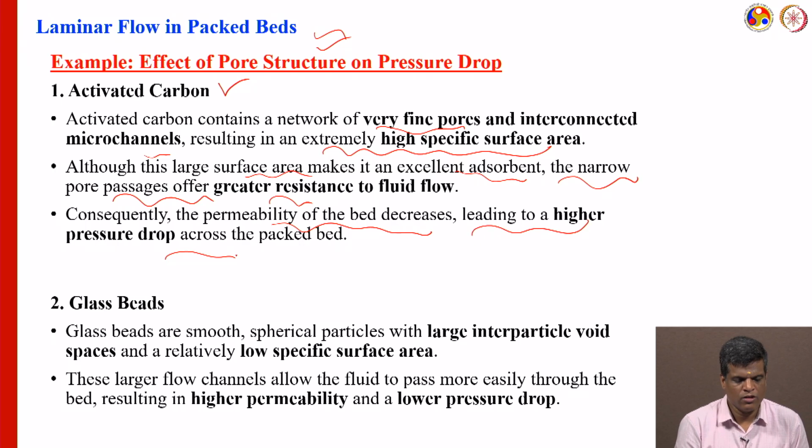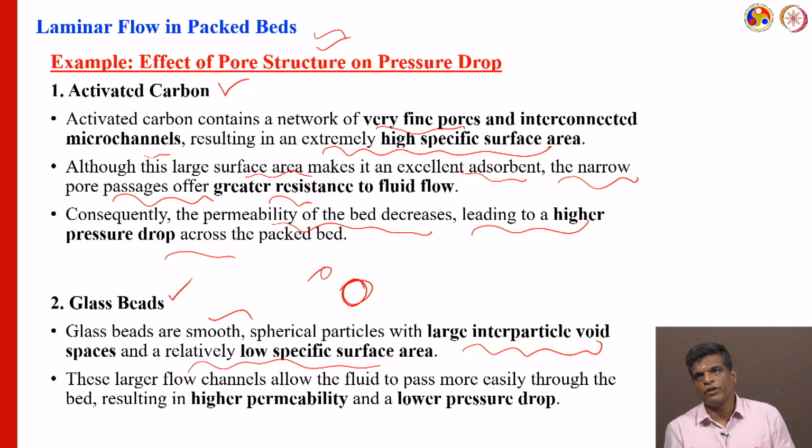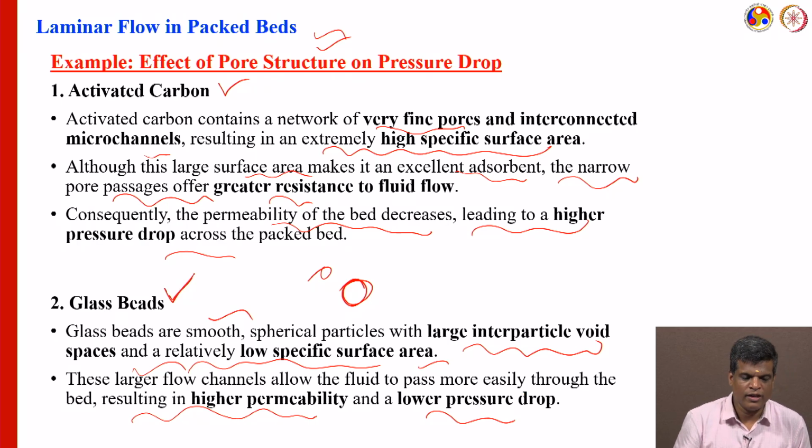If we use glass beads, what will happen? They are very smooth, spherical particles, but there are large interfacial void spaces and a low specific surface area. These larger flow channels allow the fluid to pass through more easily, so the permeability will be higher and the pressure drop will be lower. That is the difference between activated carbon and glass beads inside the packed bed.